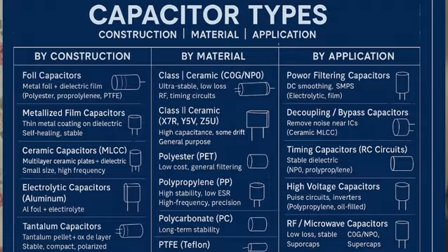By material, if you ask me, I would categorize into two classes. Class 1 is made up of dielectric compositions like C0G and NPO, and Class 2 ceramic capacitors are made up of X7R, Y5V, and Z5U. We majorly use X7R in the Class 2 example.